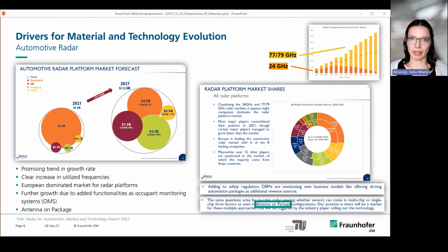At least this is the perspective from the industry, and that we see more and more the radar systems that have really elevated frequencies. Actually, in research, you already see 84, 91 gigahertz radars, 122, 140 gigahertz, and when you move away from the automotive application towards sensing-related applications, you see systems even beyond 200 gigahertz.